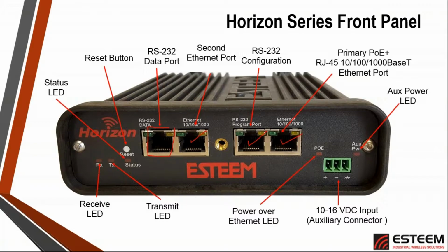Now it looks like an Ethernet port because it has the same physical type connection, but electrically the lines inside of that port are RS-232. We keep it as an RJ45 connector, quite honestly, for the size of the interface. To put a 9-pin port or a 25-pin port or any other type of common serial port there just takes up too much real estate.